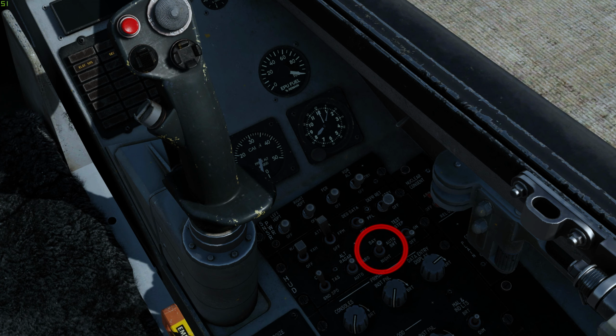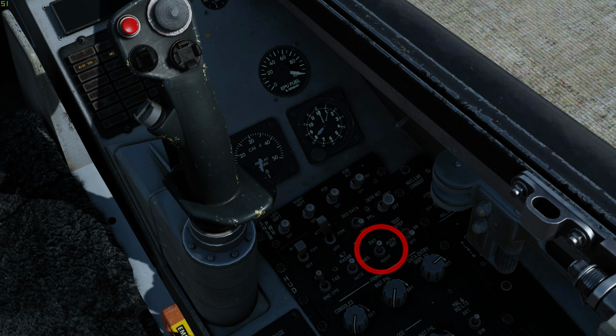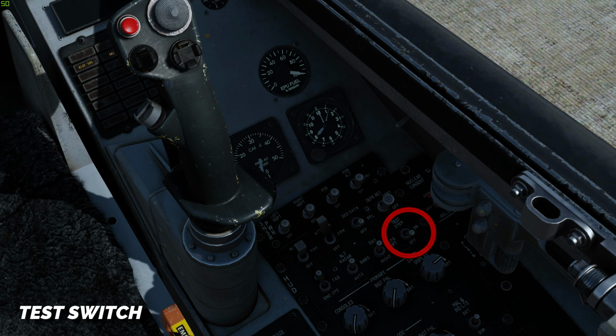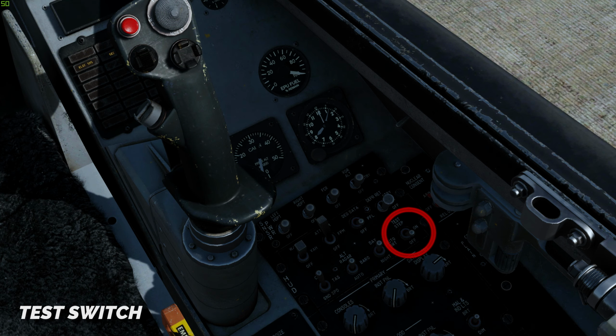The ABC adjusts the brightness of the symbology depending on the ambient light intensity. The range of the automatic setting is 1/100th of full intensity to full intensity. If the ABC sensor fails and the brightness switch is set to automatic, brightness will default to the day setting. The test switch controls the display of 4 HUD test patterns.